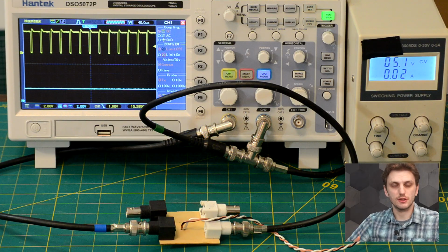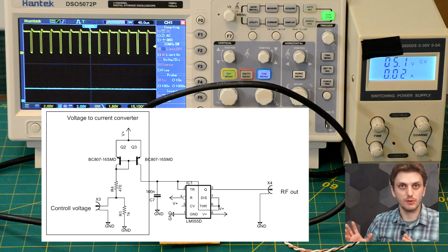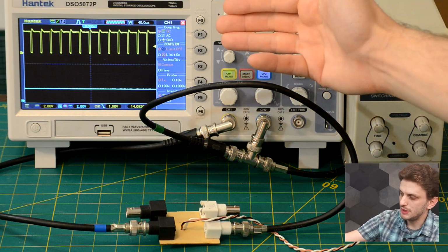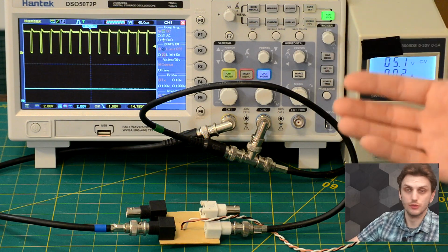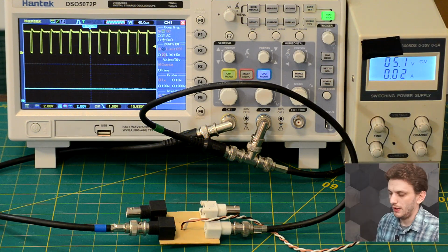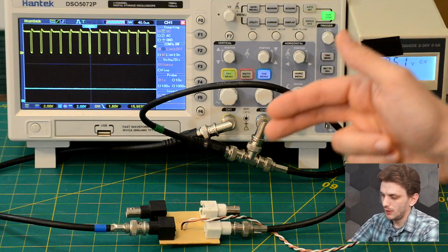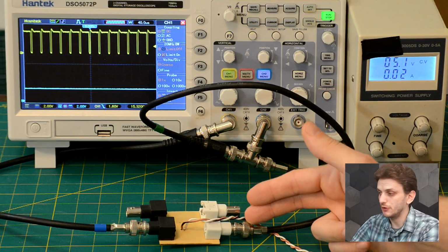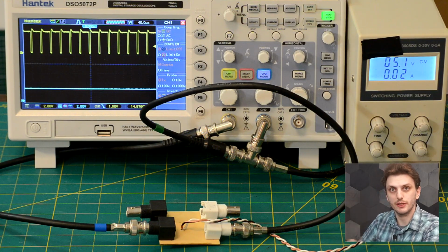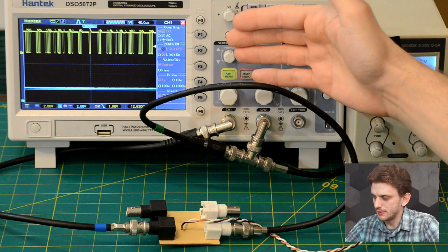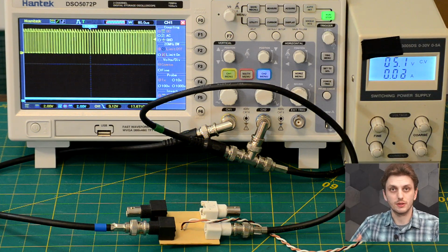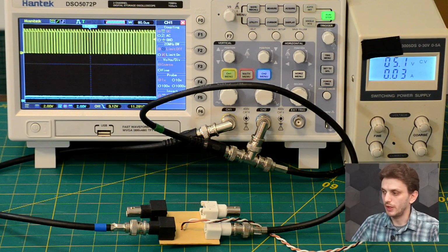So first of all, this is the oscillator built with the 555 with the simple current mirror. And if we look at the waveforms, well, we can see the output being almost a square wave, so it's not completely perfect, but it's good enough for our experiment. And again, with a fixed input into the circuit from the signal generator, nothing is happening. But if we change that, if we apply the same triangle wave, we see that we have quite a substantial variation in frequency.